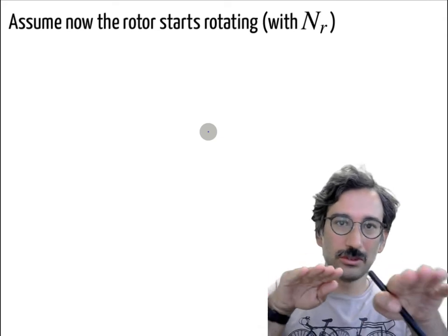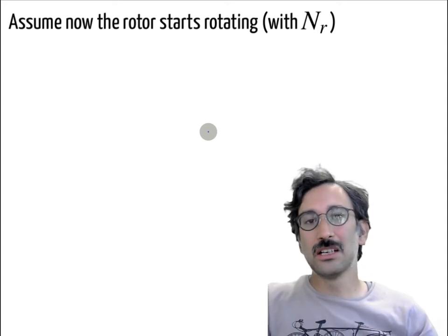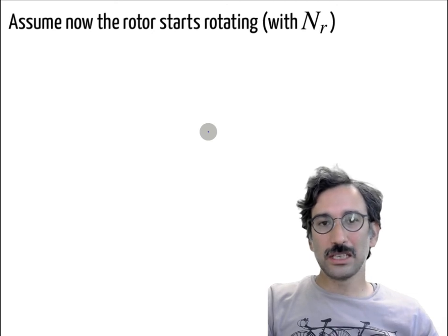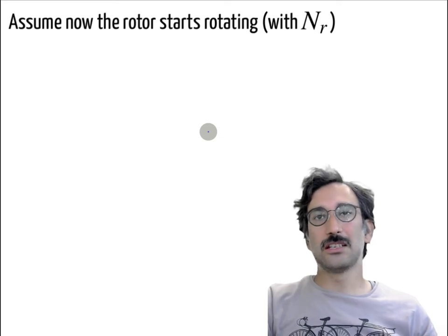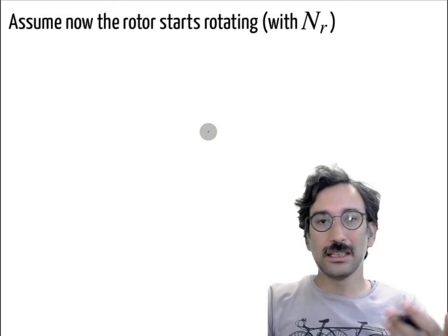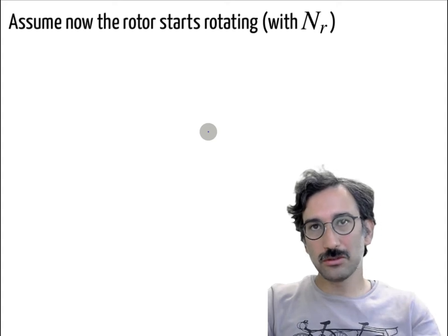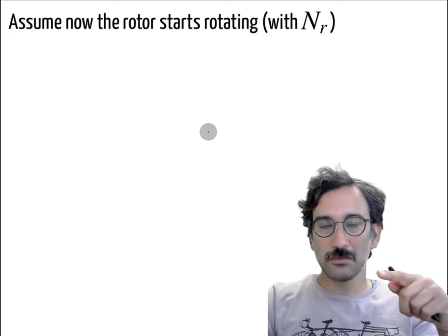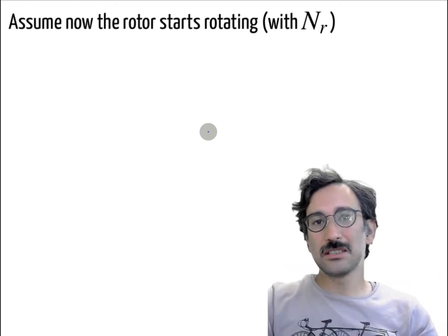Okay, remember, like two trains, you are looking at the other train and you see the difference of these two trains. So that's the same logic. So when it is rotating at 10 Hertz, the current's frequency drops to 40 Hertz. If it speeds up to, I don't know, 20 Hertz mechanically, then the rotor frequency drops to 30 Hertz, and so on. And for example, if the rotor starts rotating at 45 Hertz, then you have 50 Hertz stator excitation still. So the difference just becomes 5 Hertz.